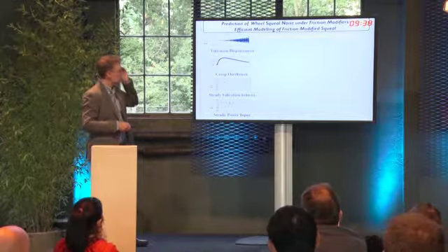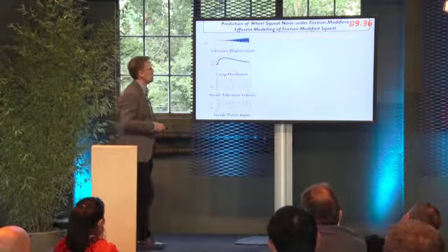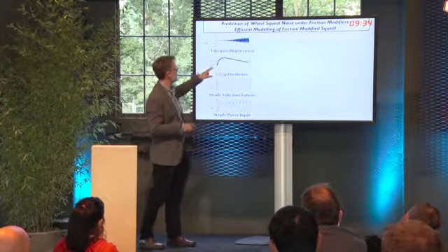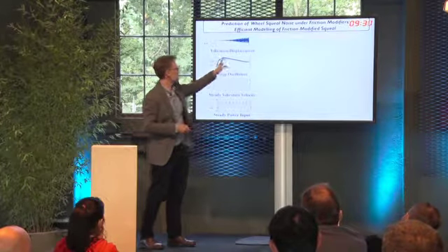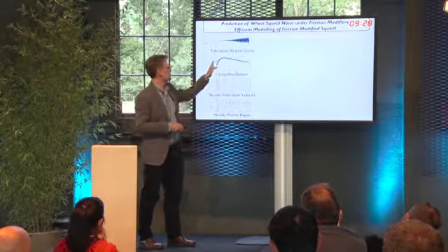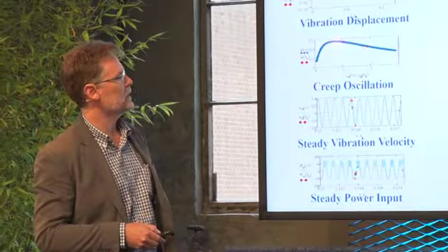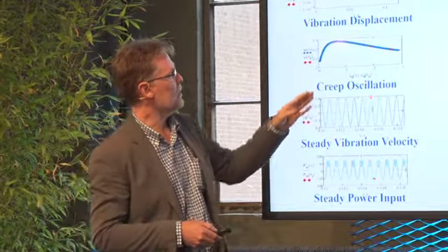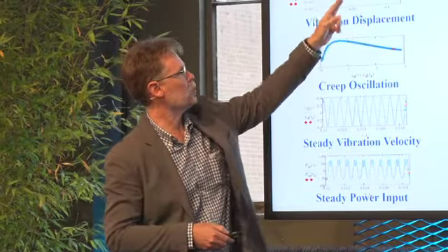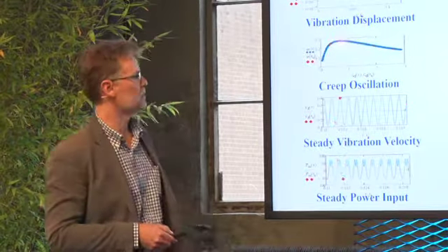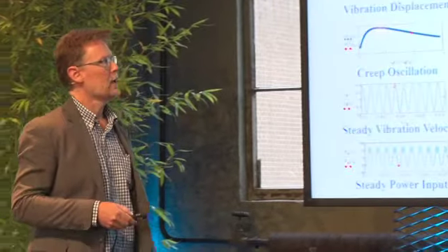A little bit more on that: you can see when the squeal occurs, along with the vibrations of the wheel, you've got oscillations in creep. Now, it's this negative slope region which is actually causing the growth of the vibrations there.